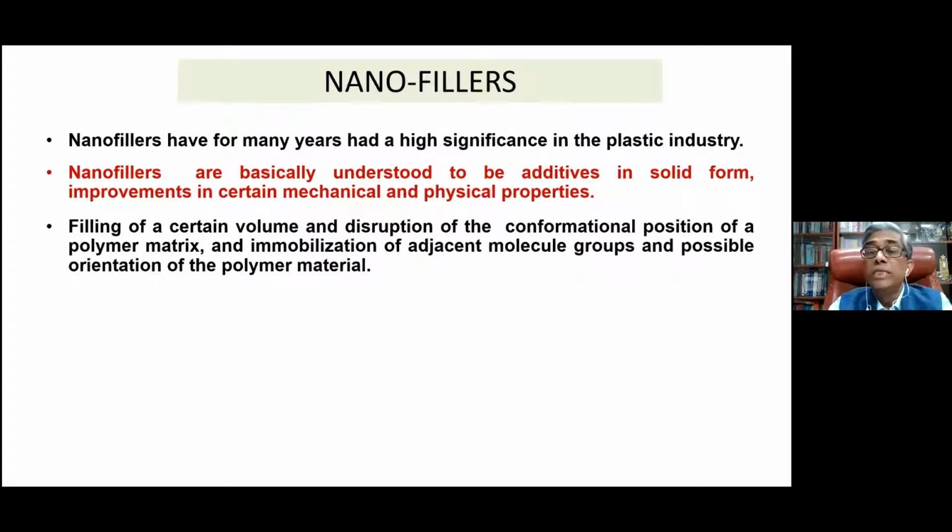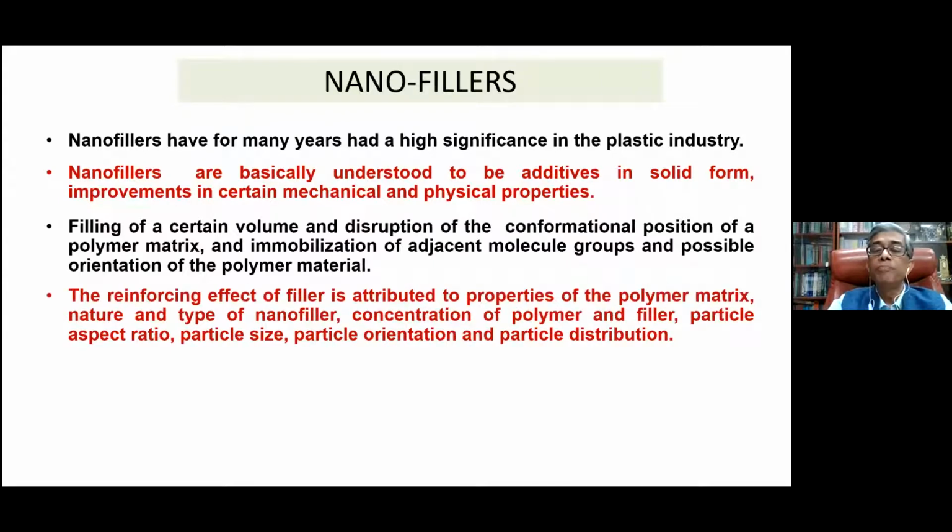That's why we say that if we can use nanofillers properly, we change its modulus. You'll see that your modulus changes by 2 times, 3 times, like that. Okay, and it makes something rigid. So its thermal property also changes. Okay, and the reinforcing effect of this filler actually depends on the nature of the polymer matrix and the filler, what type we are using, what kind of concentration we are using, what is the aspect ratio. So just saying filler will not do.